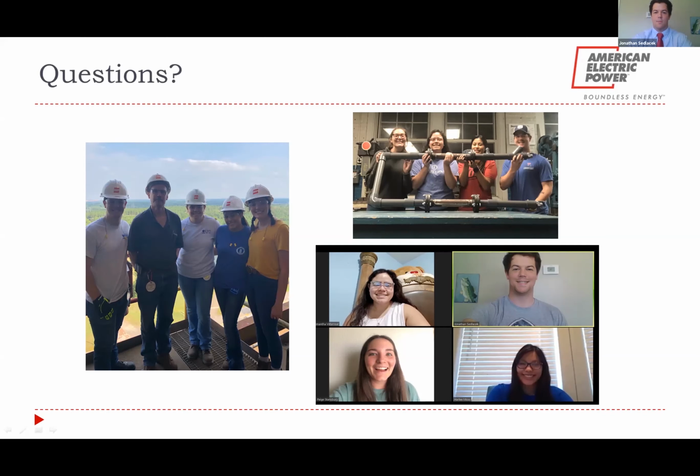I'll take that one. Titanium was being used by the researchers at Louisiana Tech long before we started working on this project, but probably the main reason that titanium was chosen for their situation and then for our application was just because of how uncorrosive it is. So it's very unlikely to corrode in environments like this one, where we're basically forcing the corrosion of, in this case, the electrolyte, because there is no real anode in this situation. But if it was made out of something else, like copper or any of the less noble metals, we would have seen a lot more corrosion, which could have broken the electrical circuit or left wire inside the piping system, which both would have been bad.